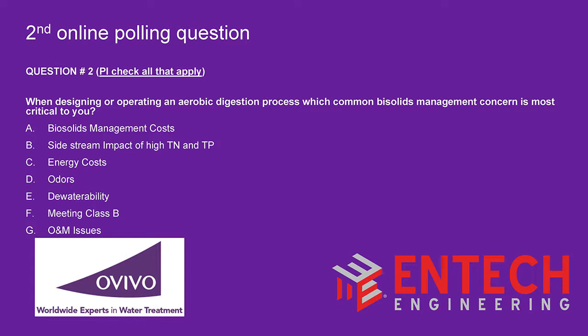And of course, with regard to one of these items, we've already told you one of the benefits of saving energy by putting in the proper amount of oxygen is you actually are denitrifying. You're actually getting rid of the nitrogen that's the ammonia that's being released. So avoiding putting too much oxygen in produces a lot of benefits here.